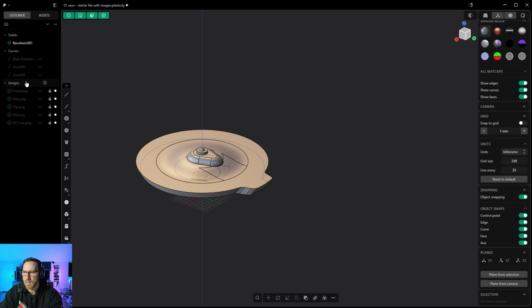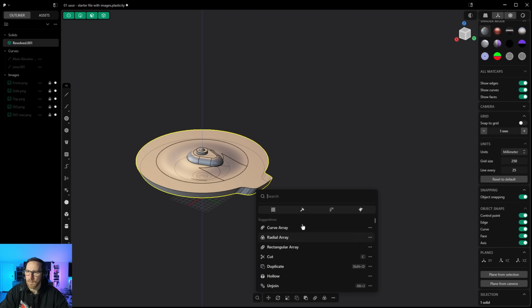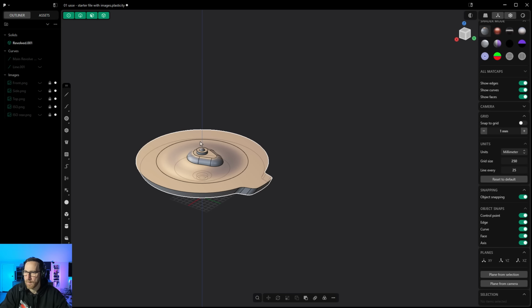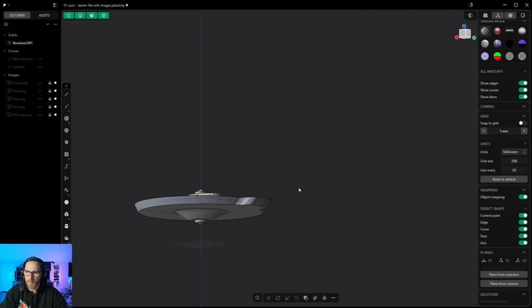I don't need that rectangle or that line, so I'm just going to select and delete those. I'm only going to keep curves that are the main geometry. And then again, we're going to select this and start to type in delete redundant topology, and then that'll just clean up all those extra cuts that we made.